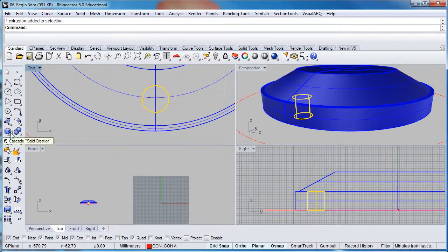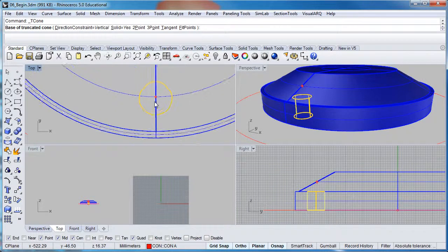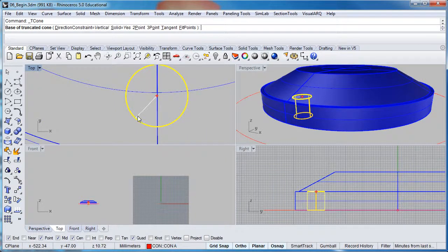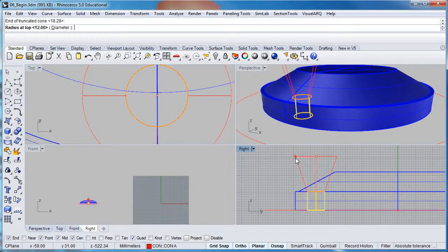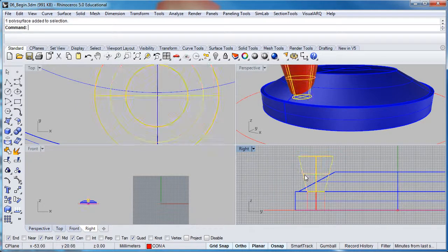So the geometry that we're going to create is a truncated cone. We activate the little blue triangle, drag to the side, and you can see right in the center, truncated cone. There it is there. We've already got center activated, so if we float our cursor in the middle there, it's in the right spot. We drag out to the side, you can see it's activated. Then we drag up ever so slightly if you look on the right side view, and we've now made the countersunk. Great, excellent. So we've got two pieces of geometry.